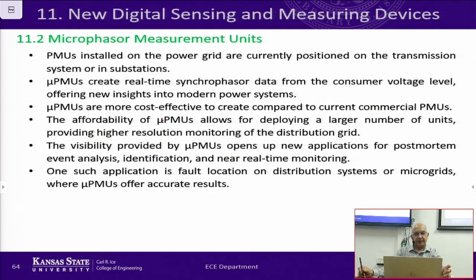Now, in addition to the PMU, there is also discussion about micro phasor measurement units. PMUs are pretty much for transmission systems, so people are talking about low cost PMUs for distribution system applications. They are called micro PMUs, and they can be used in distribution systems at critical locations. PMUs have been deployed quite a bit, but micro PMU is more at an experimental stage.